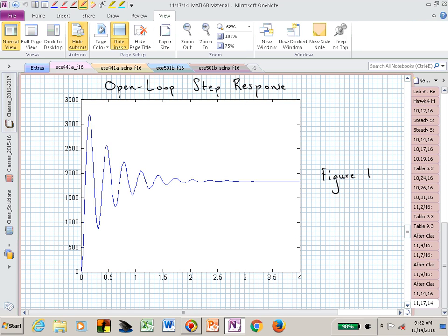And so in the lab, maybe after you hit 1 or 2 humps, if you have a weak spring, you only get 1 hump. The momentum isn't enough to carry you on as this ideal linear system behavior would demonstrate. In the lab, the friction and the things we aren't necessarily modeling kind of dominate, and now you have just 1 or 2 humps before you settle. So the theoretical settling time might be longer than what you see in the lab.